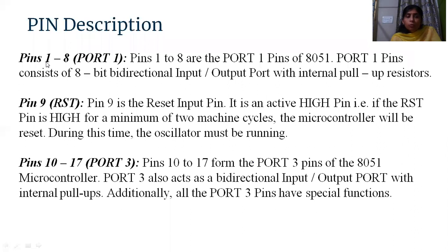As I have told you, pin number 1 to pin number 8 are port 1 pins. This consists of 8-bit bidirectional input and output ports for taking input and giving output to the 8051 microcontroller.